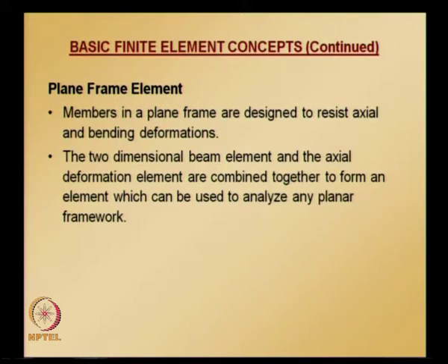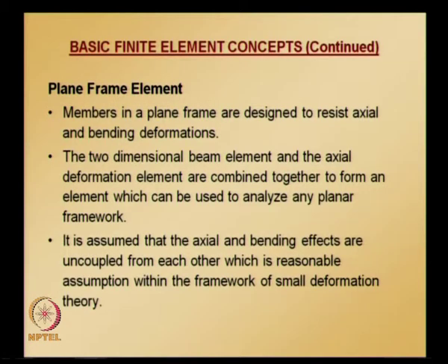While doing this it is assumed that the axial and bending effects are uncoupled from each other, which is a reasonable assumption within the framework of small deformation theory. So the equations for a plane frame element can be written directly from axial deformation and beam bending equations that we looked at in the earlier lectures.